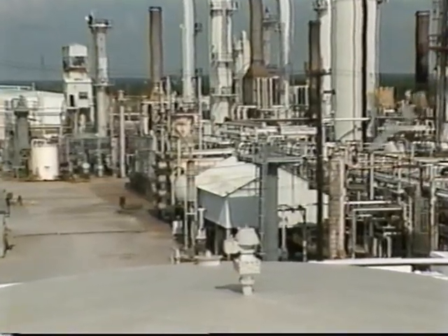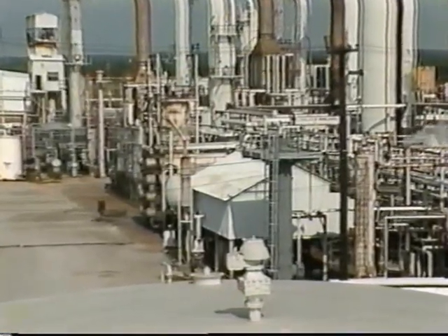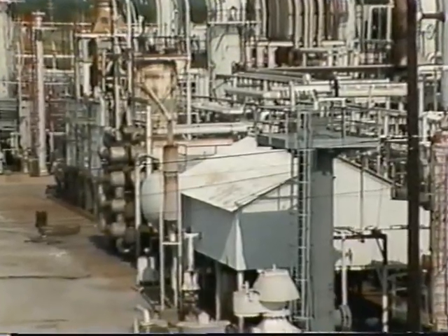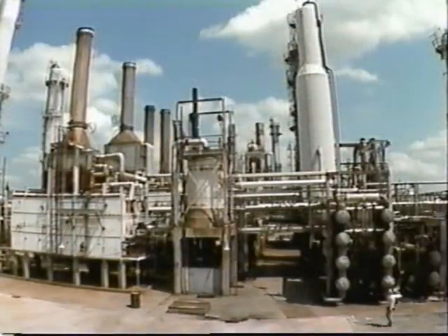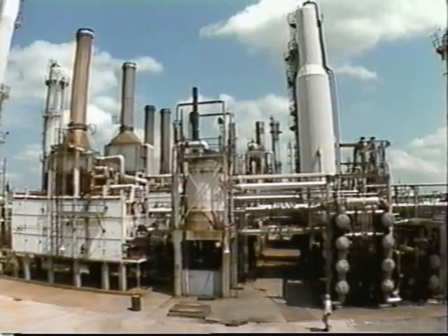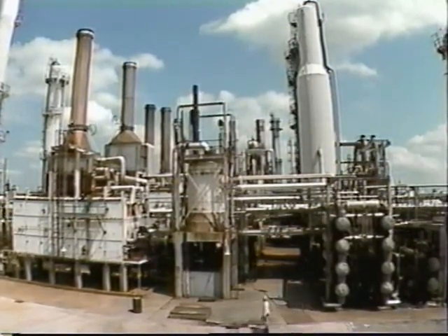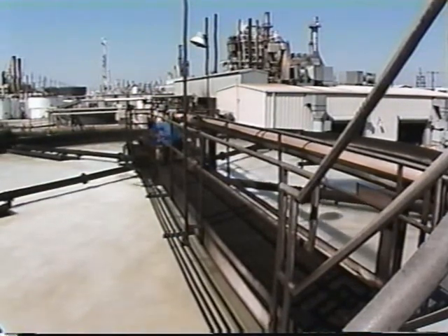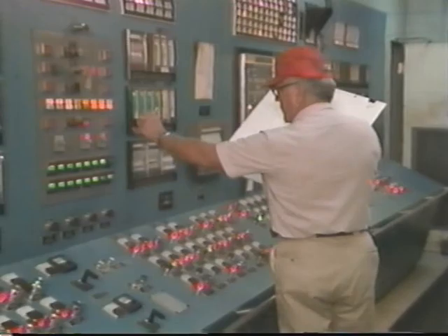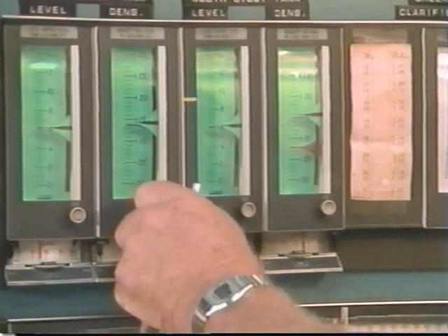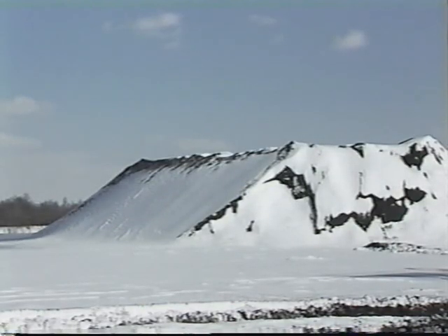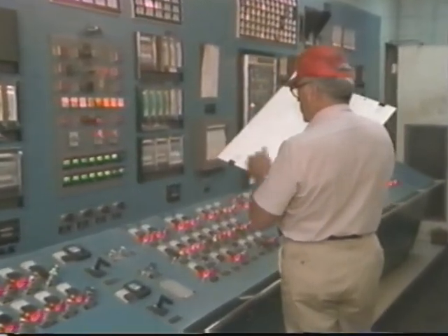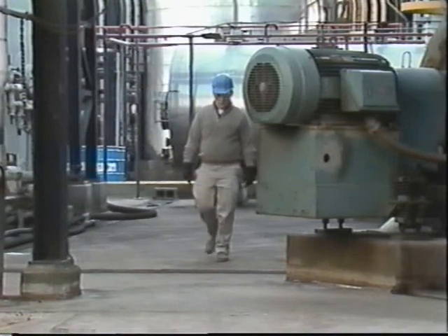Another thing to consider is whether the problem occurred while the process was in a steady state condition or was being started up or shut down. Sometimes a change in the operating conditions or environment can lead to problems in the process. For example, a recent change in the feedstock to the process, an increase or decrease in production rates, or even a sudden change in the weather. Each of these can be an important piece of troubleshooting evidence for the operator.